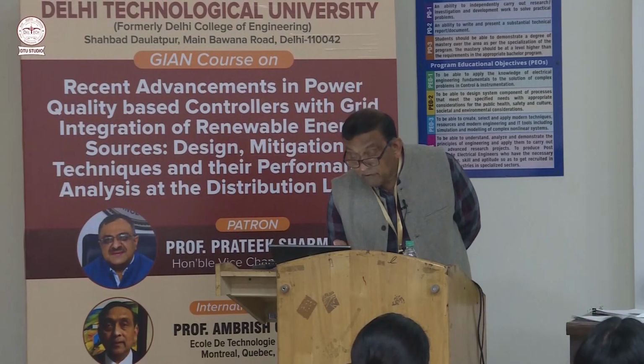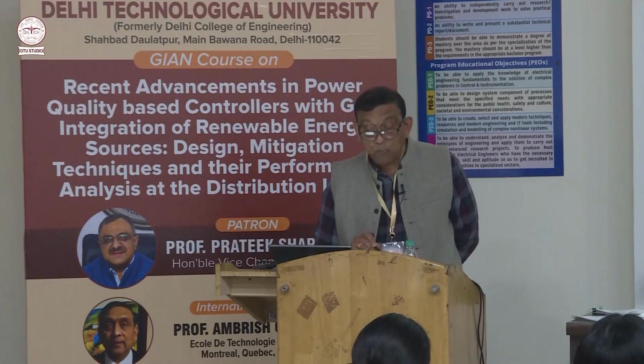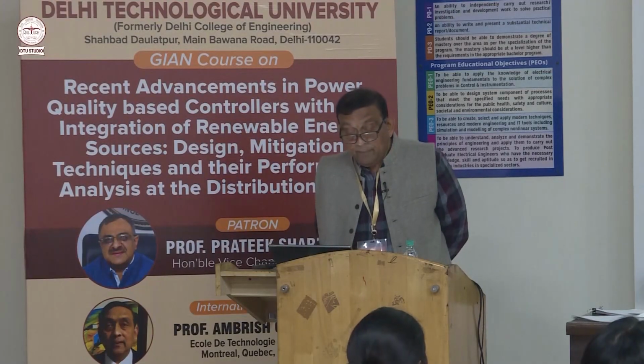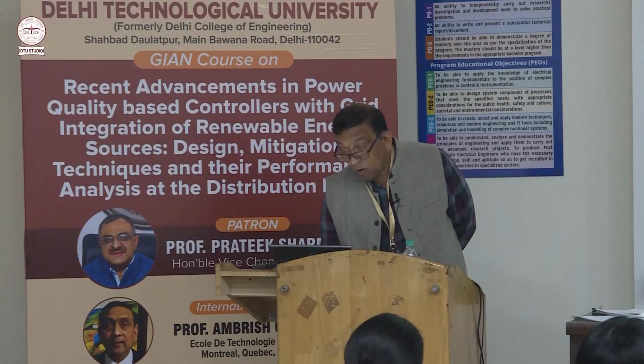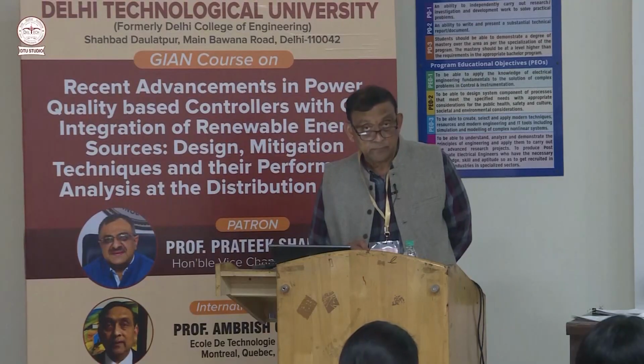If the rectifier was already installed, many methods are available to improve power quality, like you can put passive filter, active filter, hybrid filters, right? But in certain cases, the capacity of these filters become the same as rectifier capacity.